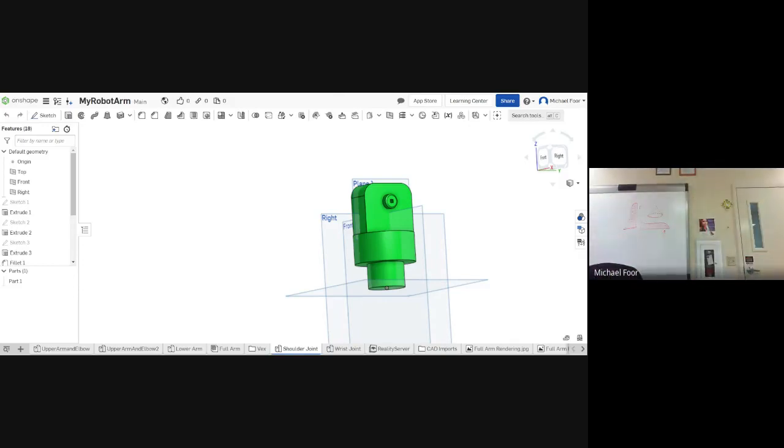What's up? To make something hollow, you need to have a hole in the center. So when I'm going to sweep it, now that's a pretty abrupt curve, so the curve might be a little too extreme, but let's give it a try. So sweep. Now just click on the outside one. Yeah, that's your face right there. Click on sweep up. Bend it. Yeah, that's just too sudden there. If you can see it turning red, that's because it's intersecting with itself and bending over itself.